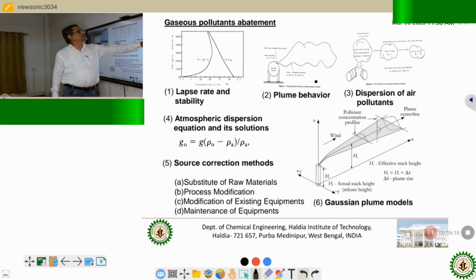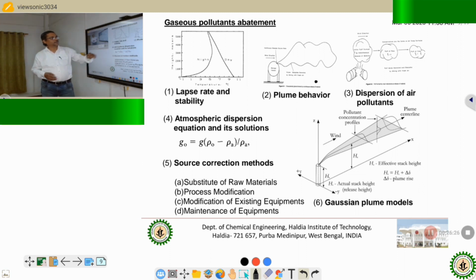Next one is the dispersal of air pollutants. In most cases the continuous cloud has less mixing capacity with air. But if we release the toxic vapor at certain intervals, by using pop-up valves, the valve release is not continuous. Within a fraction of a second, it is releasing and closing. So the volume of the cloud generated will have a smaller size, and it will be mixed with air properly, so that it will be carried over in the sky, and will never touch the ground. So in that way, if we know the techniques, we can control all these situations.